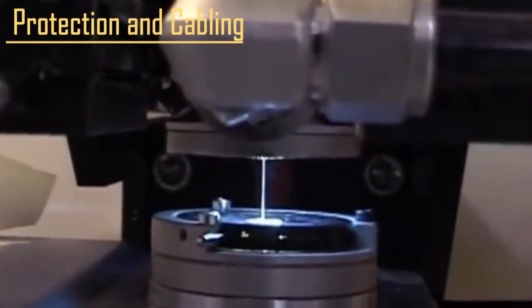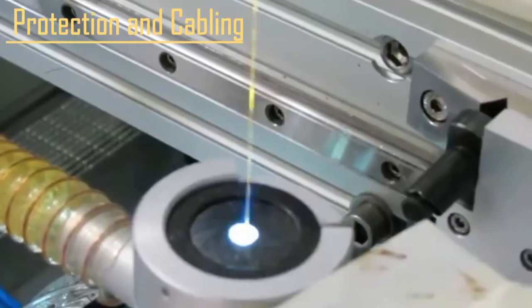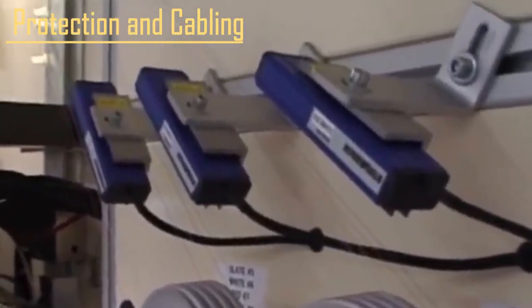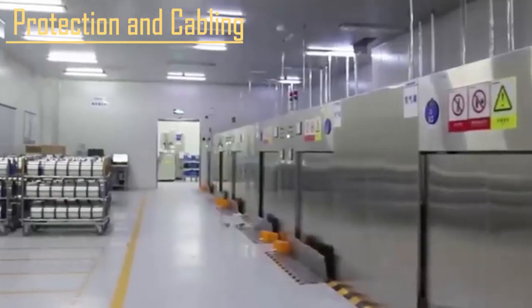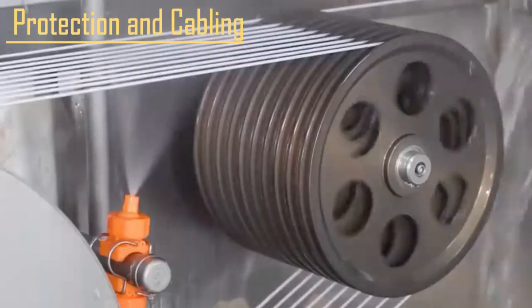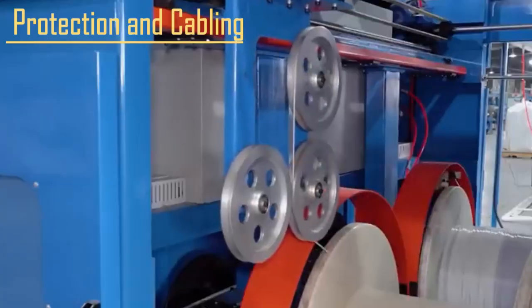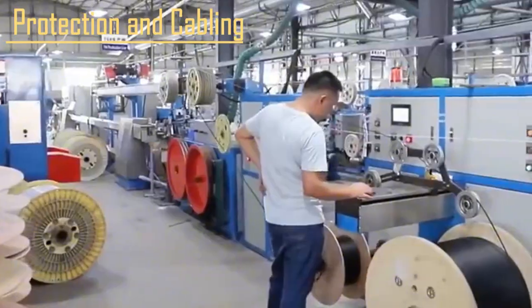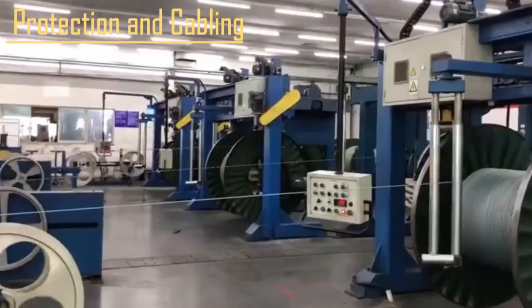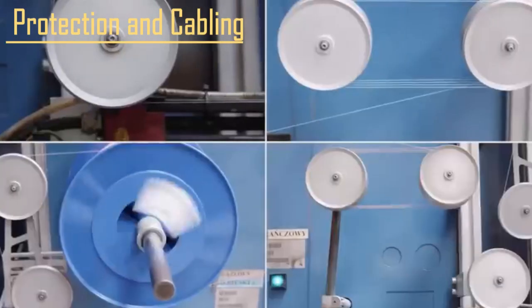The fiber then runs through an ultraviolet UV curing system, which instantly hardens the liquid polymer into a transparent, protective shell. The now protected fiber is continuously guided onto massive reels at the base of the tower. This high-speed winding process must maintain steady tension, as any excessive pulling or uneven winding can crack or deform the delicate glass. A single preform can produce continuous reels of fiber, ready for the next step.